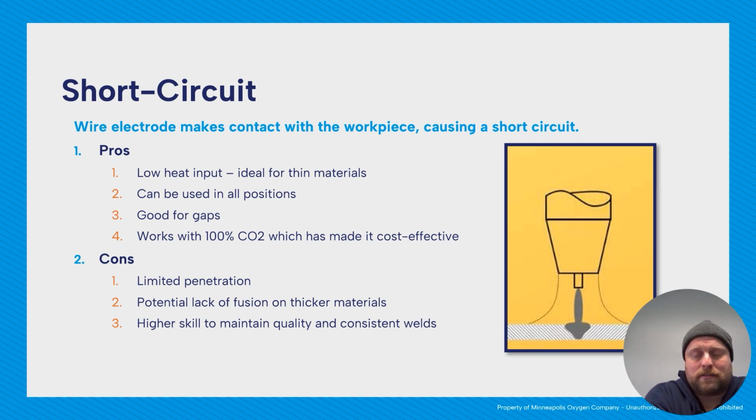The most common transfer mode out there in the world is probably short circuit, as far as what most people use. Industry-wise, maybe not, but when you consider the part of industry that uses it, plus home hobbyists, people who have a welder in their garage, that sort of thing, short circuit's where it's at. Short circuit is where the wire electrode makes contact with the workpiece, causing a short circuit.